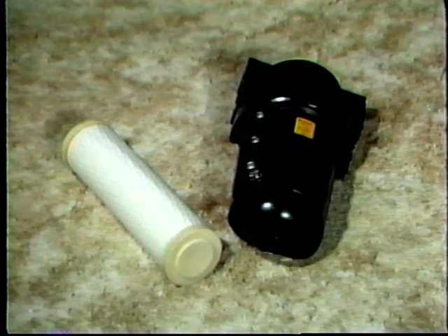Filter elements, like those we've just described, will do a good job of removing hard and soft dirts, and most of the entrained liquids. But if you need air that is almost completely free of contaminants, you'll have to use one of these, an oil removal filter. They come in many different sizes and shapes, but they are all designed to deliver very clean, oil-free air to the workstation.